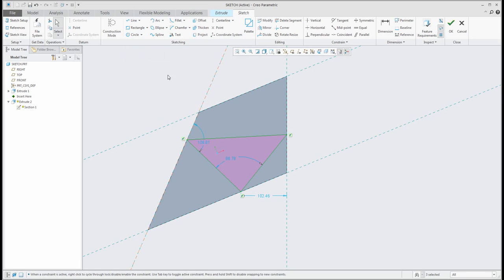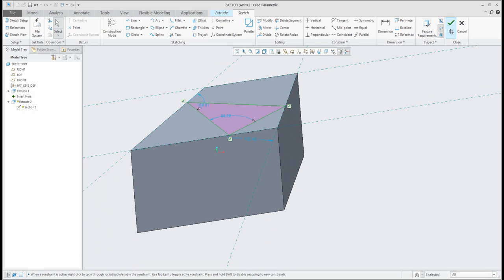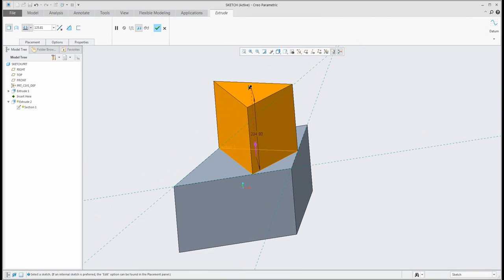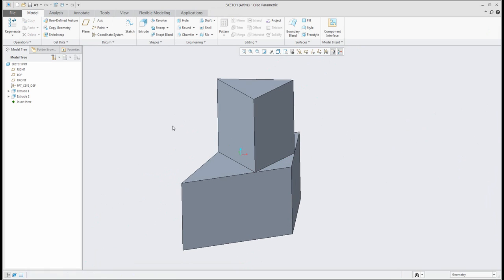And what about the other features? I will go straight on and create other features, so we can add other objects, for example extrude, and continue. If I create the extrude feature and I go straight on, you can see here that we would like to create, for example, for this extrude feature directly in the sketch, the axis. Yeah, for what is it good? Because next time I'd like to use it here, some hole on this axis.